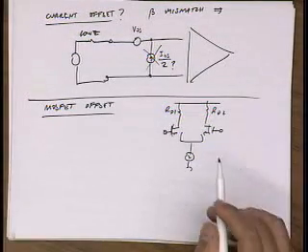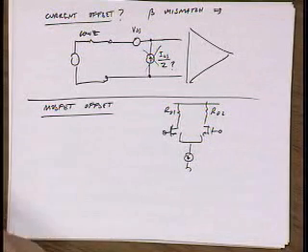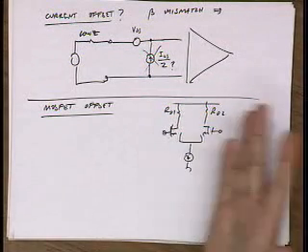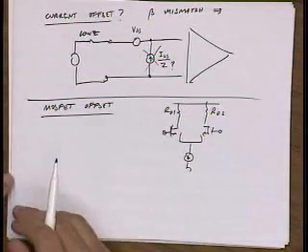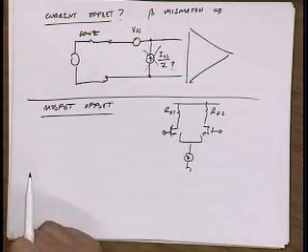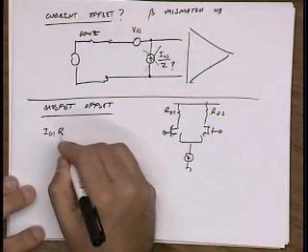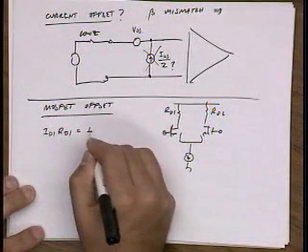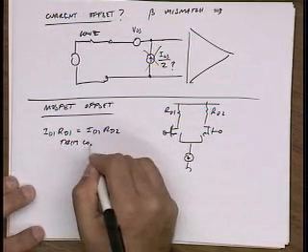Now, in a real MOSFET amplifier, you don't have resistors here, right? You have a current source, and so then you'd have to calculate the offset in your current source. I encourage you to do that calculation or read through the book. So again, under the trimming conditions, I'm going to assume that ID1 RD1 is equal to ID2 RD2. This is the trim condition.